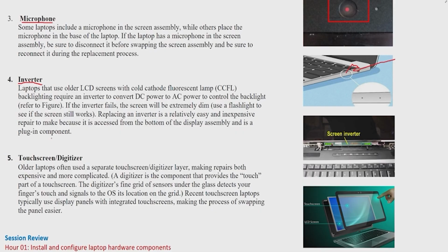If this chip is broken, there will be no display. Your display is fine, your LED is fine, but because this panel is damaged or something happened to it, there will be no power, because the inverter is what gives power. Sometimes you have seen that you always have to connect the charger with the laptop. Why? Because this panel is not working.